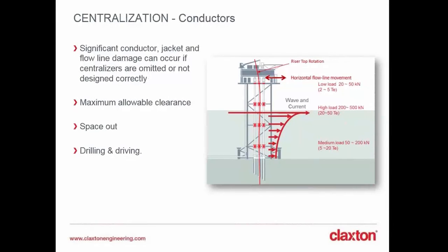Once you've taken care of the centralization of your drill string, then we also have to look at centralization of the conductors. Significant damage can occur if centralization is not considered, and this damage can be not only on the conductor but also on the jacket guides and on the flow lines as well.